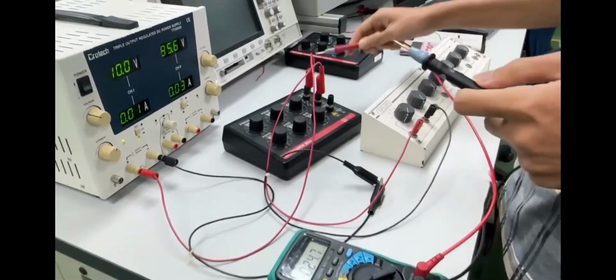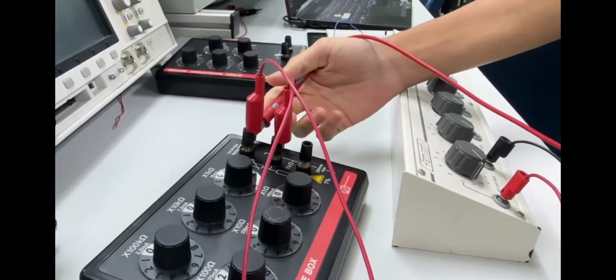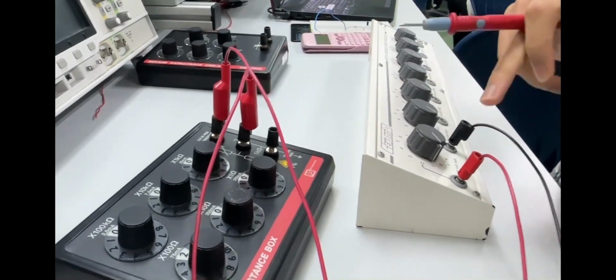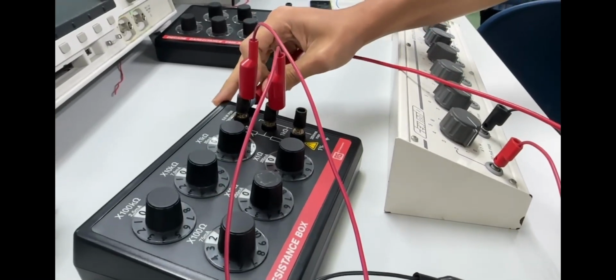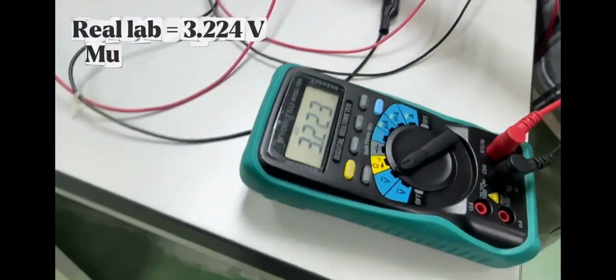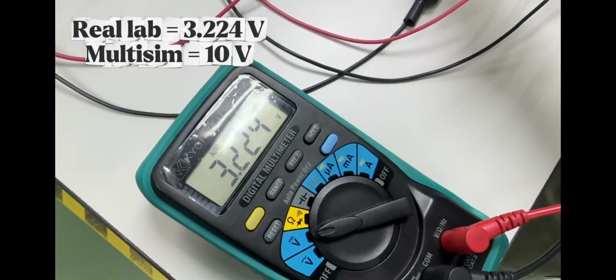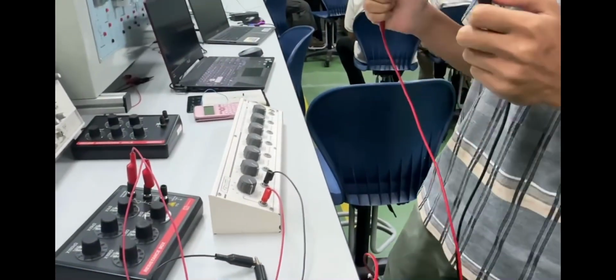Now the positive of the multimeter goes here. Here is the input for the resistor, and then the output goes to the inductor. So we need to put the positive side of the multimeter here, and then the negative goes here. Okay, we will get 3.224 volts. That's the measured voltage value for the resistor.